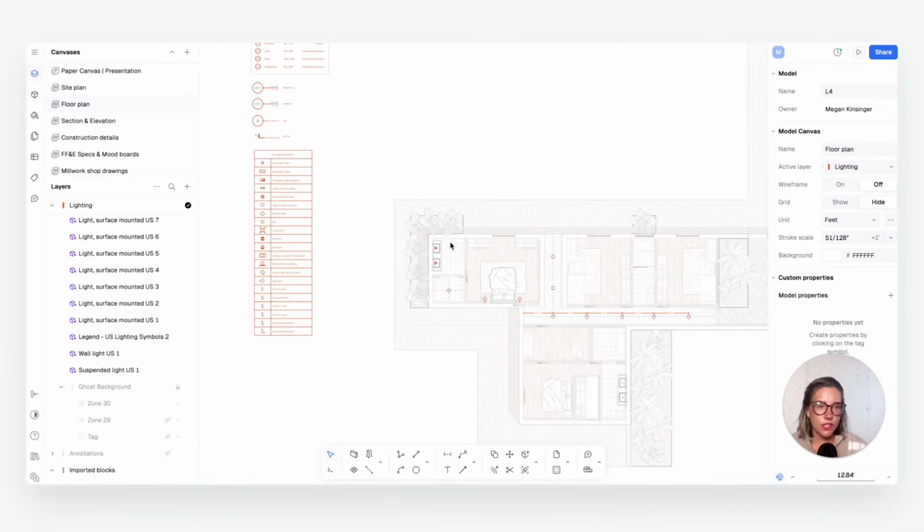Next, we want to consider the switches and circuits and the whole functional planning of this electrical plan. So switches and sockets are usually placed logically based on how a user uses the space, how the room functions, entry, exit points, and we are able to use some shortcuts to efficiently rotate and duplicate those symbols here in Rayon, kind of like we've done with our lighting symbols already.